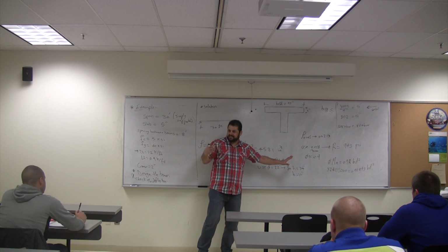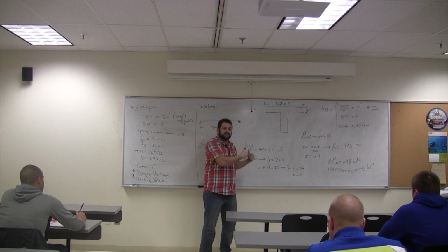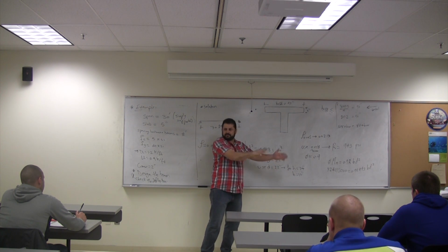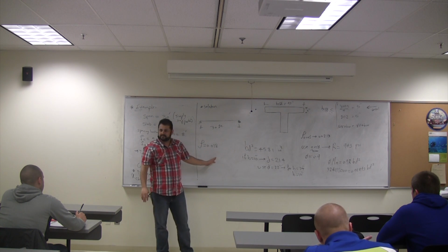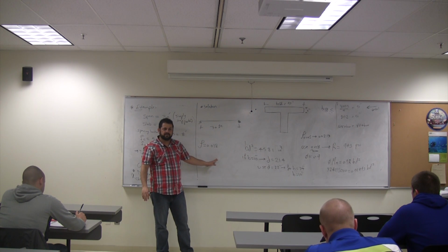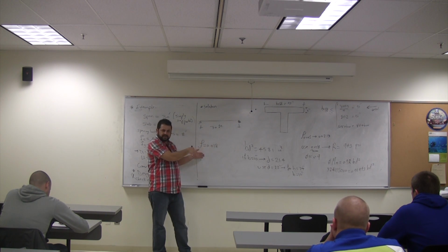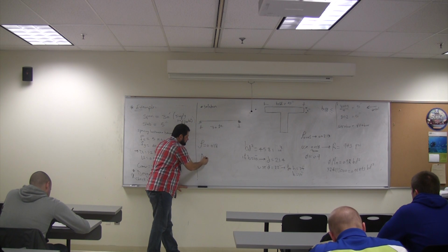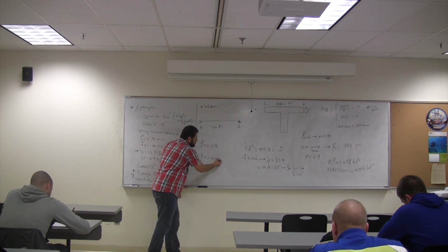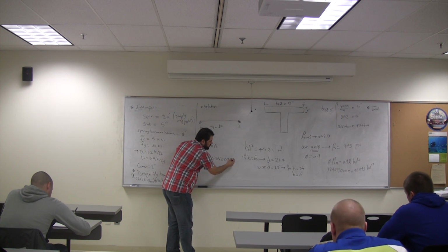Because we are generous, we said we're going to use d equal 22. That's fine, but you don't have to multiply this by the rounded number. If you multiply by 21.4, that would be fine, because anyway you're going to round it a little bit more to get the required area of steel. So As equals 0.018 times 10 times 21.4.